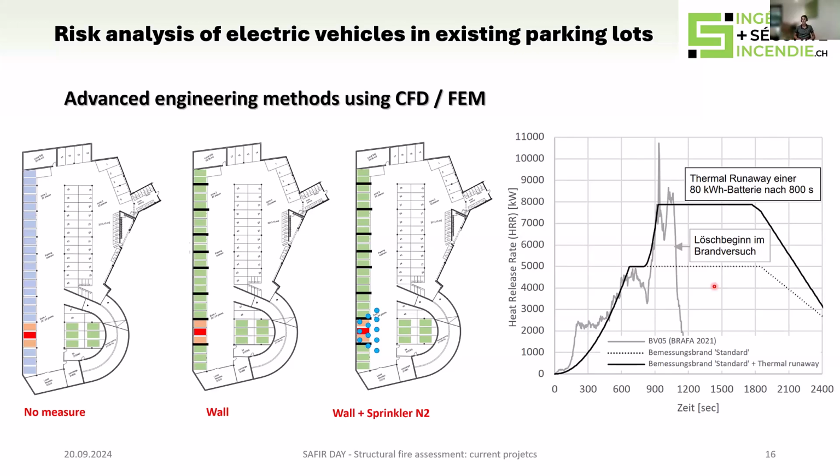On the right, we have the fire design curve, which is quite new in Switzerland. This curve is based on very recent experimental tests, and this curve is recognized by the Swiss authorities to be adapted for electric vehicles because the plateau at 8 megawatts considers the thermal runaway of the battery.